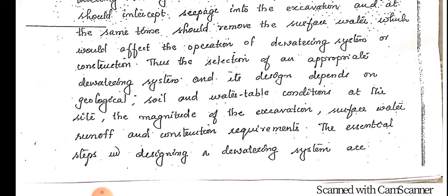So, we studied many dewatering techniques, right? Many dewatering methods like well point, deep well, electroosmosis, etc. So we studied different methods. Which method has to be adopted at a particular site depends upon factors such as geological factors, soil and water table condition at the site, magnitude of excavation, surface water runoff, construction requirements, etc.